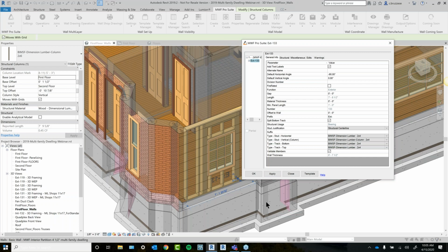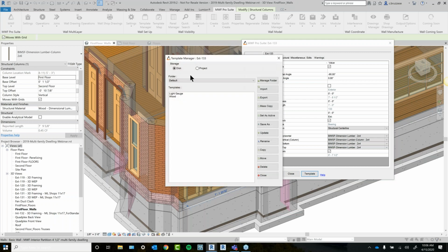Now to save it, I'm going to hit apply. That's going to apply these changes to my wall panel without me having to leave this window altogether. Now you can come into your projects tab, and I can just hit save as.